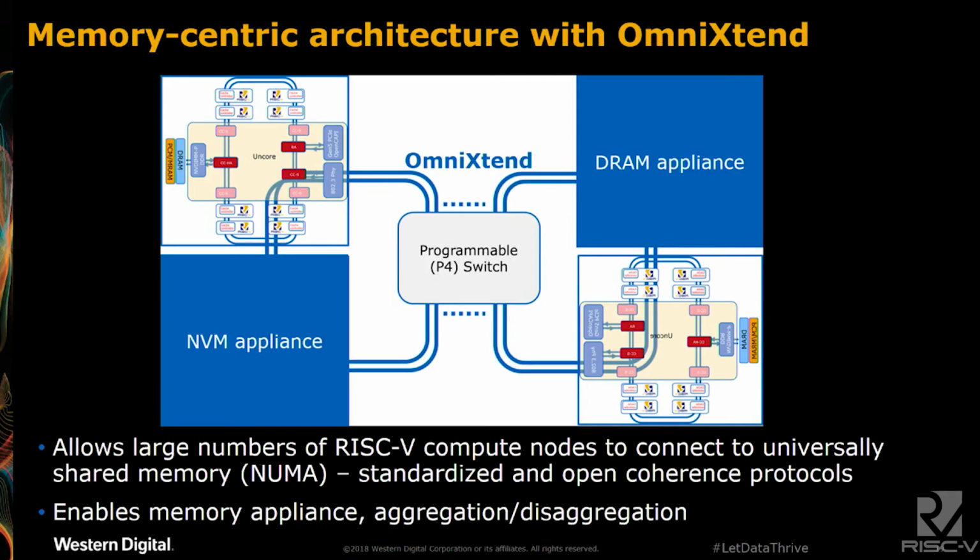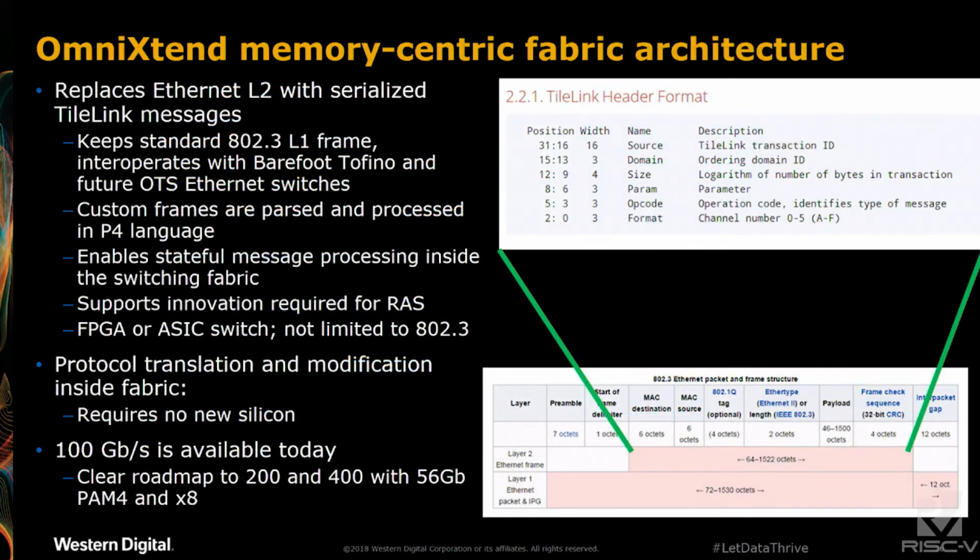And so we're a storage company. Why do we care? Of course, we want to sell you appliances that you plug into, and they show up as a giant main memory. So how does it work, right? Like I mentioned, these new Ethernet switches are programmable. The language is called P4. You can either use an FPGA, with Xilinx SDNet as one option if you want to play with it, or you can buy a Barefoot Tofino switch off the shelf. They're at 6.4 terabits per second, and just today there's an announcement of a 12 terabit switch coming out in a few months.